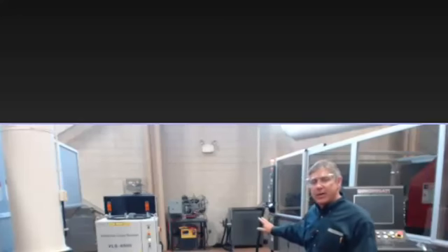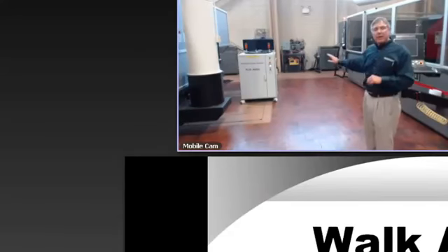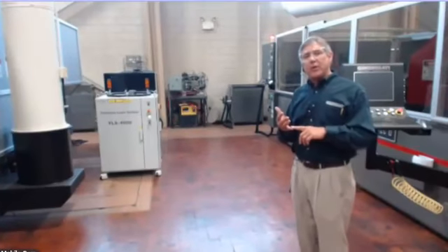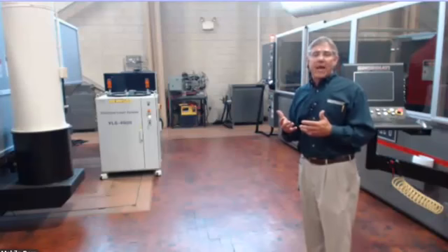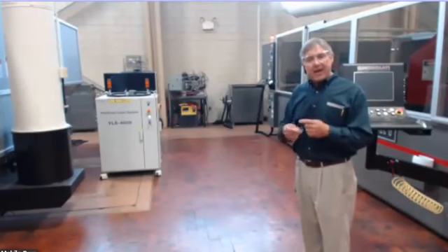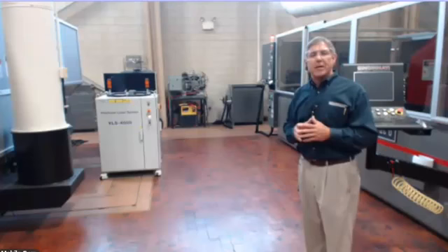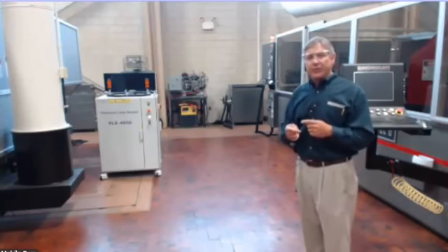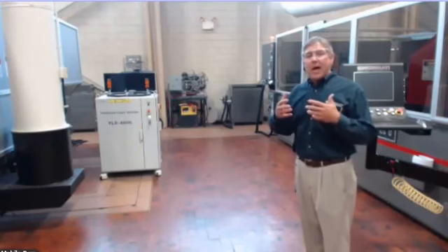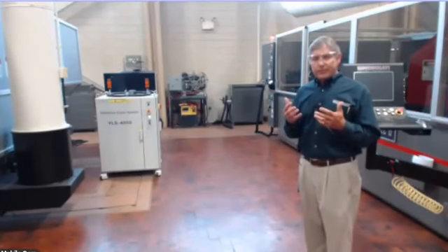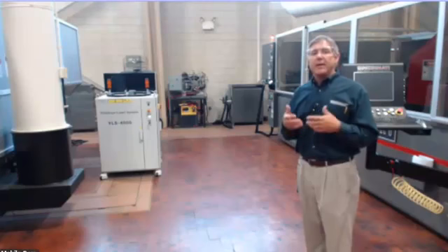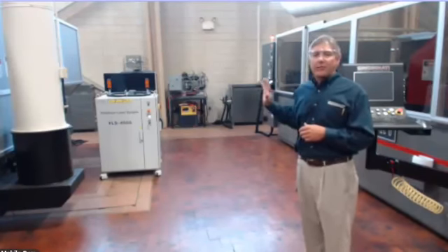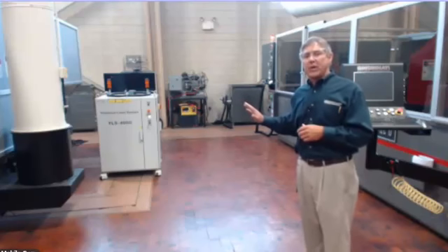Well, on the CO2 machine, we have gas bottles that would bring the laser gases into that resonator. There's a mixing panel to get the proper mixture of those gases. There's some high-speed fans or blowers or turbines, whatever terminologies you're comfortable with using, that will circulate those gases through those glass tubes at a very high speed, and then a very high voltage electrical voltage is applied to that and develops a current and generates then the photons that create the laser beam. So there's some maintenance costs and just some maintenance management associated with the CO2.